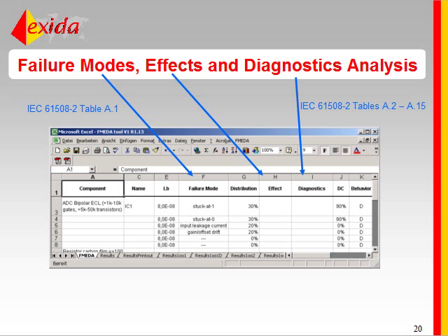The result of that is a detected or an undetected failure, and the mode is dependent totally on what happens to the instrument, or what happens to the subsystem, if you want to call it that. So the end result is, for each particular failure mode of the instrument, we have total failure rates, and of those failure rates, we know how many of them are detected and how many of them are not detected.